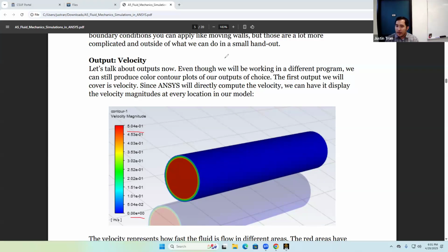But just like the deformation, remember, deformation is a vector. And so not only does it have magnitude, it has direction. Now, in structural simulations, we didn't worry about that all too much, because in structures we can actually get ANSYS to display the deformation by actually deforming the model itself. So let's say you have a cantilever beam and you apply a force. When you show that result in ANSYS, it actually looks like the beam is bent. So not only do we get the numerical values for the deformation, we can visually see which direction the deformation is moving within the model itself.